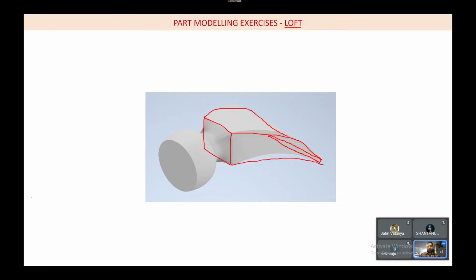So first we are going to draw, let us say parallelly, and then we'll see how to make it inclined. I'm going to offset from this plane, this side 200, or let us say I'm going to do 150. Okay, if I zoom all, you can see that we have created something here. Now I am going to introduce a new command which is called angle to plane around an edge. First we are going to create a construction edge in this plane.